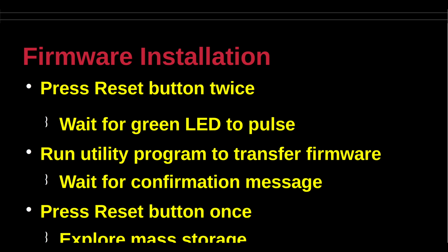After the confirmation message is displayed, press the reset button only once. It will now be possible to explore the file storage structure on the GIGA board using the File Explorer app for your operating system on the desktop.